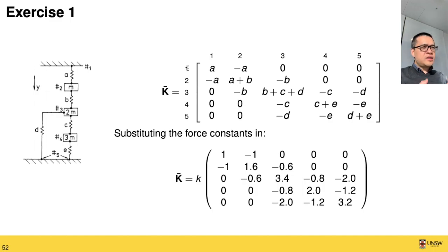And in this case, we will have the nodes being coupled together by some elements, some springs, okay? Now, this is very common in many physics problems, as I mentioned a couple of times. For the matrix, you will first have the diagonal matrix elements, right? That goes 1,1, 2,2, 3,3, etc. in this case. Now the diagonal matrix element in this case, or in many similar cases, will be the sum of the spring constants that are linked to that node.